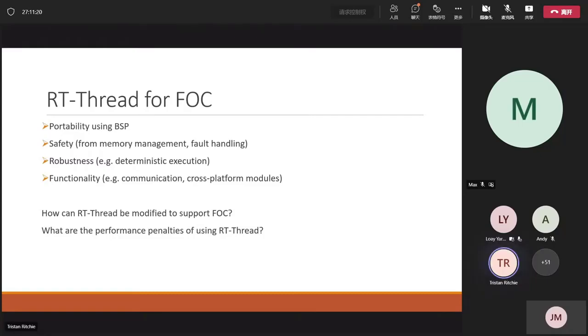And execution in general can be moderated by the real-time scheduler for less latency-sensitive controller components, such as speed control, for instance, which will generally be executed at a much lower frequency than torque control, perhaps in the range of 1 kilohertz.